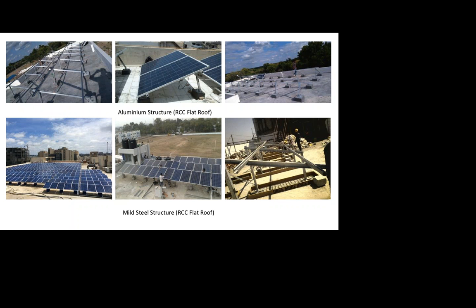Does the chemical make the roof non-porous? If I have drilled a Hilti bolt in my roof and if I apply a Hilti chemical, will it make it completely sealed off? Yeah, the good part of Hilti chemical is it being in a liquid state. We understand that when somebody drills, even if you drill a wall or the roof, there are a little micro cracks which originate all around. But the moment we put the chemical and put the bolt into it, it pushes the chemical into those micro cracks also. So to a large level, this is achieved. However, if somebody is planning to do a big project, they can get it independently tested. Hilti is fairly supportive in their test certificates.